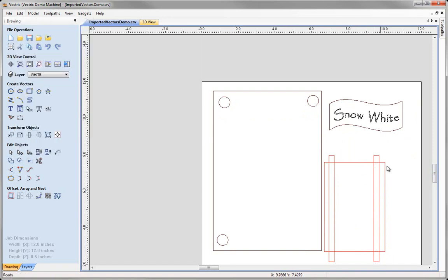Now let's look at this nice boundary rectangle that we might want to select, and when I click on it, it's not what it appears. And again, this is a really common issue, which is that many different CAD drawing packages in particular don't really have the concept of closed boundaries being a single entity in the same way that our software does. So although this to you and I looks like a rectangle, it is in fact simply 4 line segments, okay, that happen to be coincident in their line start and end points.